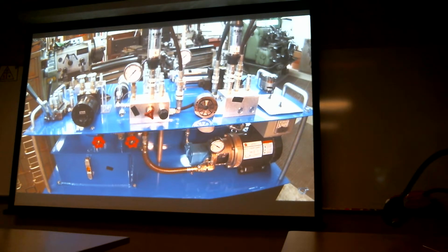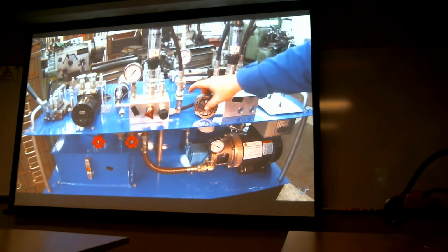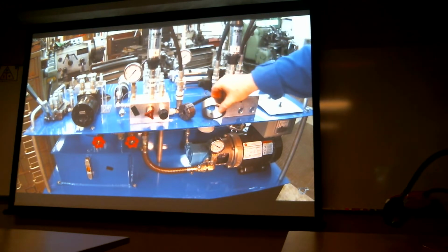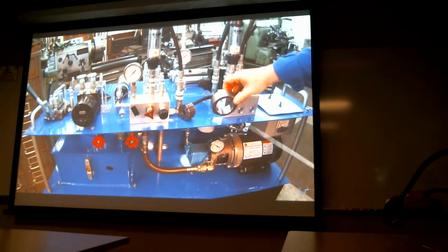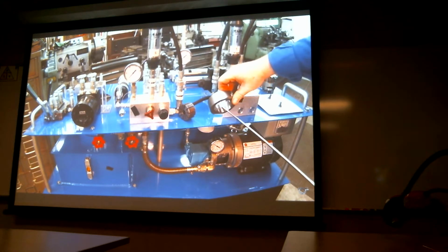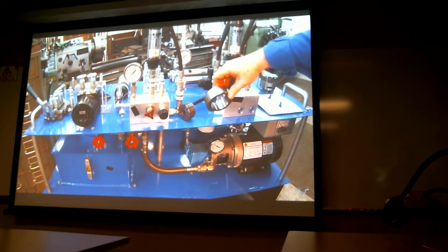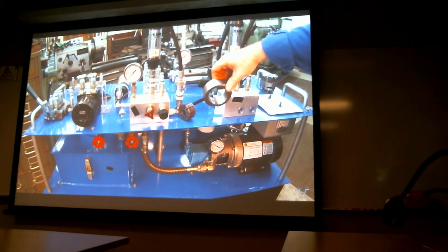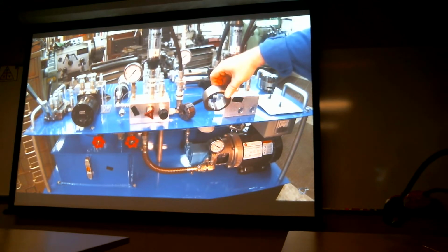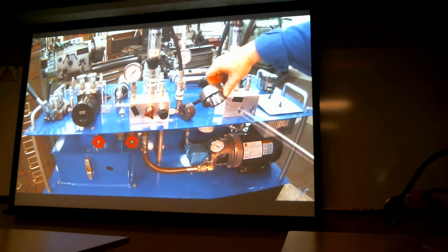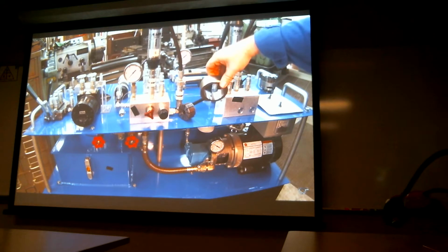Okay, so how your pump fails is when you cavitate it, you get these nice little divots right here, these little chatter marks inside your ring. So when you fail a hydraulic pump, take it apart next time and see what the ring looks like on your vane pump right here. Those little chatter marks right there say that I've got some cavitation problems. Okay?